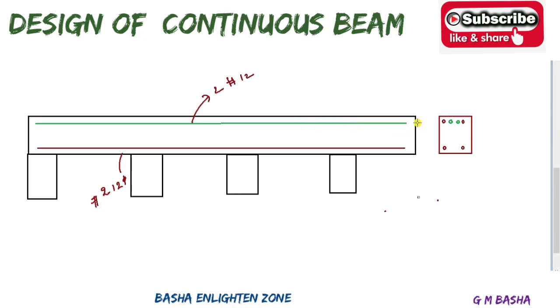But according to this condition, only the supports require 4 bars, means you can keep like this also. So you can keep like this at supports, here up to here, and again up to here, and again up to here. If you keep like that also, aside to aside, for example in one row you will keep first 1 bar and again 1 bar like this. I will show here. 1 bar, 1 bar, 2 bars as tension reinforcement, 1 bar, 1 bar, like this I am keeping. But from the side view, you will see only the front bars. So if you keep short bars only at the support also, no problem.